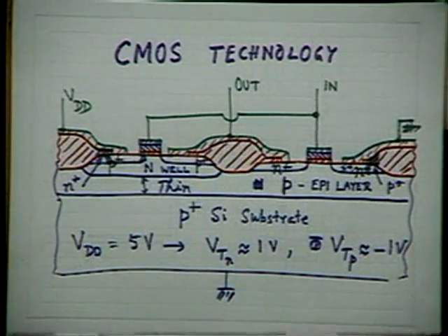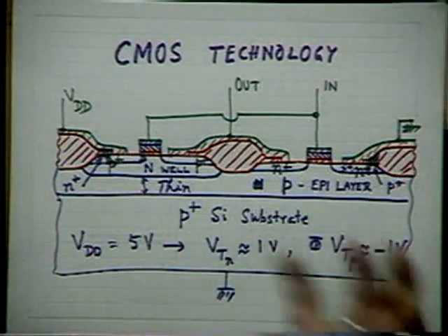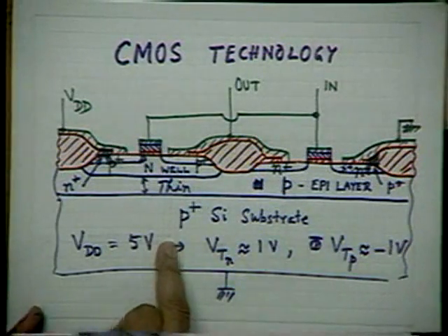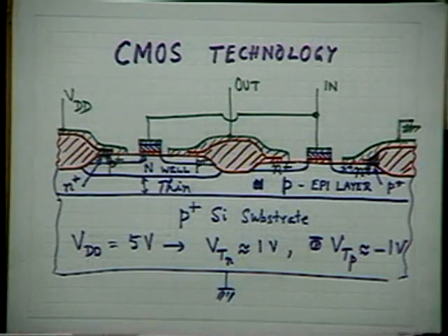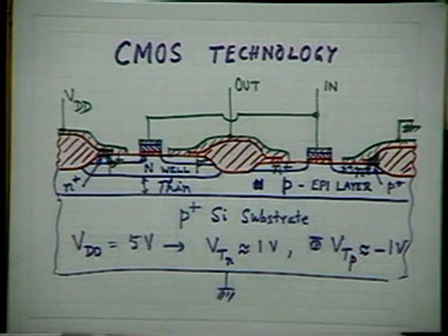Only with one transistor you can never get latchup. If there is a regeneration inside, the base of one collector of one transistor is automatically connected to the base of the other transistors. So there is a latchup circuit, regenerative latchup circuit. Then only we can have latchup. But that question does not arise if we put a P plus sink. This P plus is acting as a sink for holes, injected holes, which is kept very near the epitaxial, the N-well edge. And that's how this structure is practically free from latchup effect.